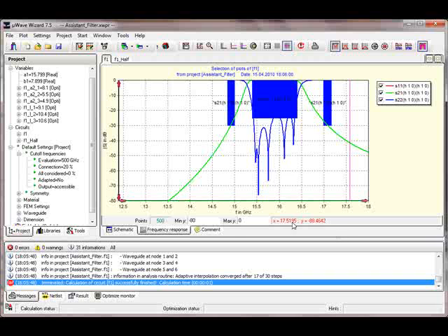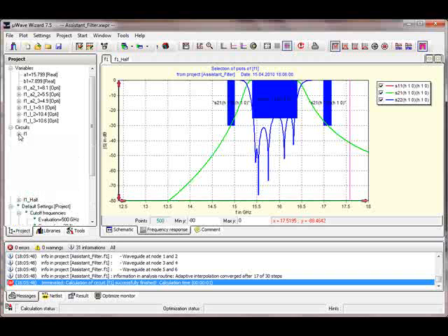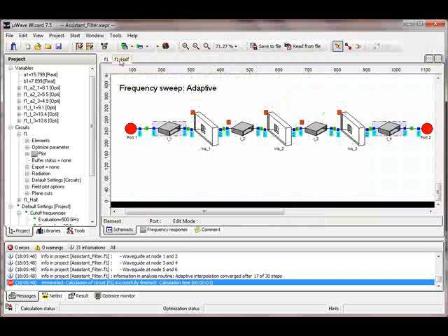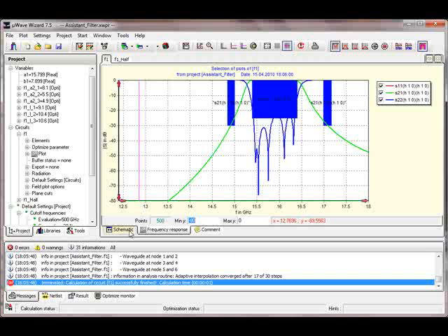Here you can see the goal function. What the filter assistant did before was already create all these settings for the optimization. First, it created the variables and set them to opti. That means it is possible to optimize those variables. And because we want to optimize the filter F1, that is the main filter, the main circuit. Here you see the half filter. It's referenced here in the main circuit.